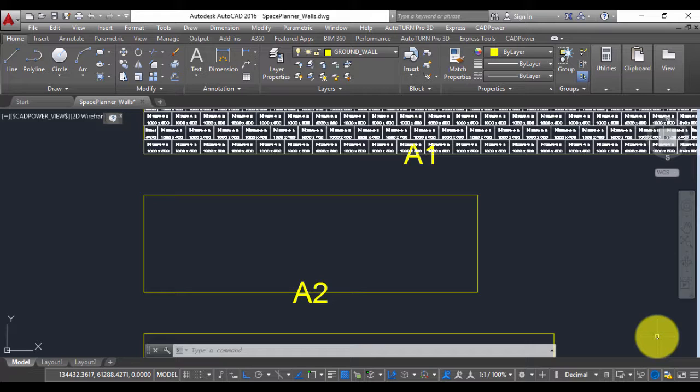In the last quantity takeoff video, we showed you how you can create tiles and place them on a rectangular or other polygonal area and create quantities out of it. In this example, we are going to show you a slightly different workflow. We are going to place a single tile and then offset it and create multiple tiles and then adjust the sizes and scale factors. This workflow is suited for creating formwork where you have a rectangular size and you place it along a wall or a floor.